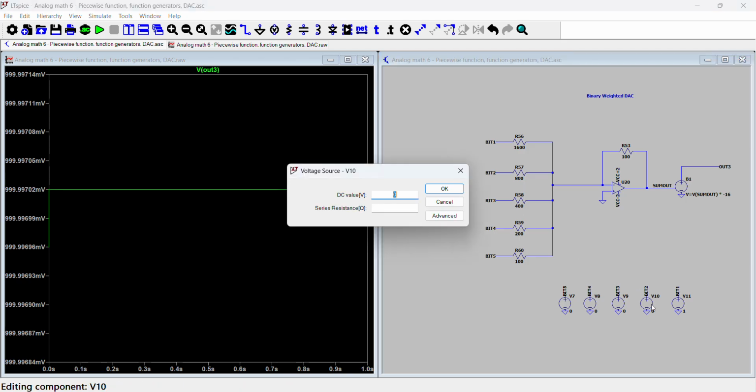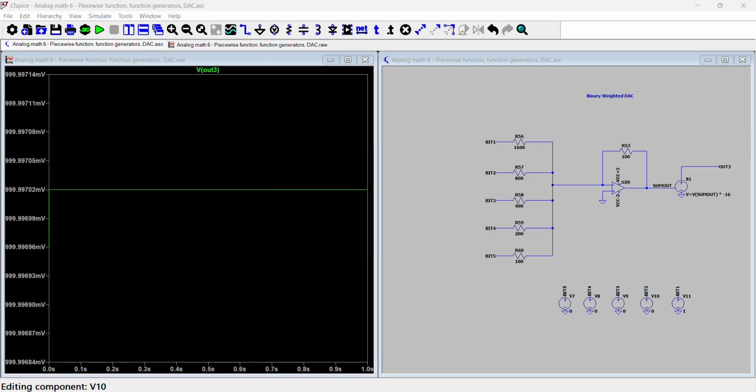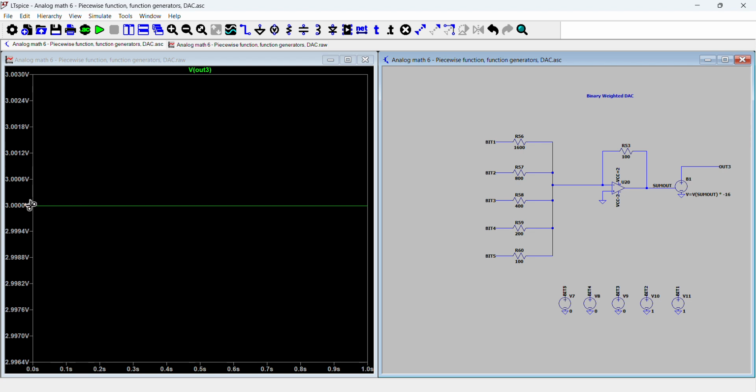And then if we added this bit as well, you can see that the output is all of a sudden 3 volts, right? Because now both of these are contributing, and the second bit is twice the voltage of the first bit. It's the same voltage input from the pin, but because of the voltage divider created by the adder, it's going to be twice the voltage contribution of the first bit, and so on and so forth.